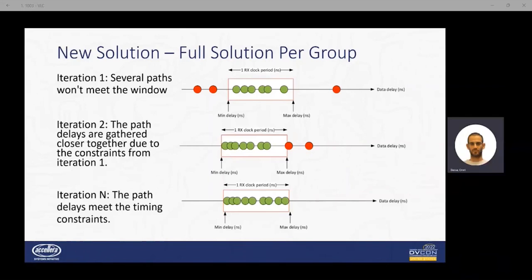And each mask synchronization scheme now meets the skew requirement since it enters this window. So the qualifier and the delta bits arrive together. So it doesn't matter if we have 10 different synchronization schemes here. Even if only one of them needs to meet the skew requirement, we'll constrain all of them together. We'll make sure that the one scheme that does need to meet this skew requirement is meeting it.